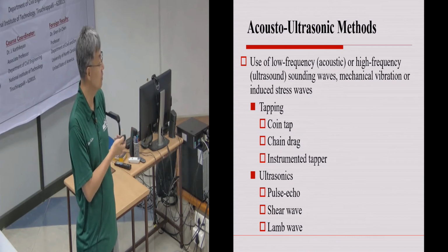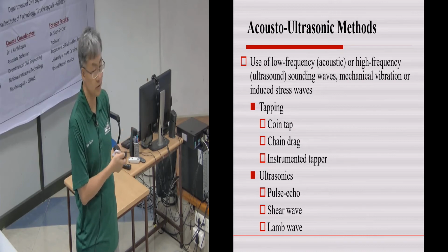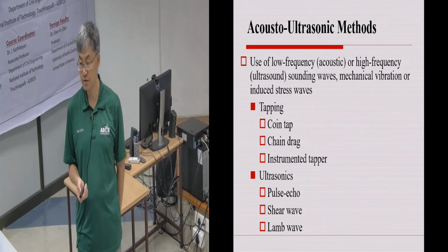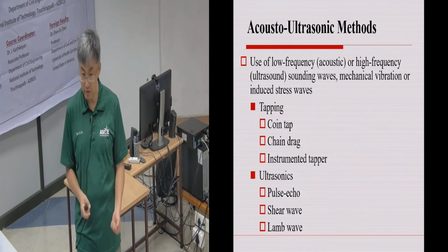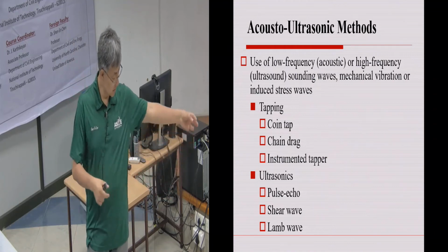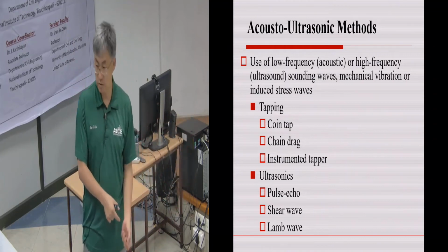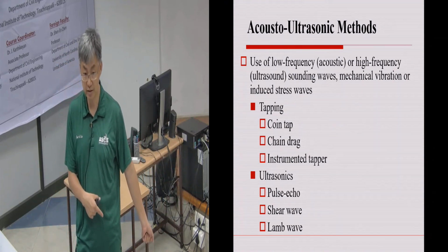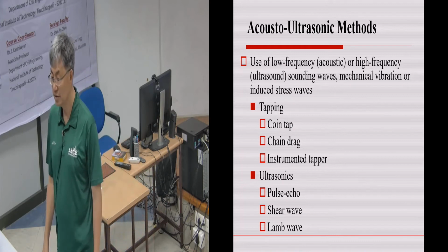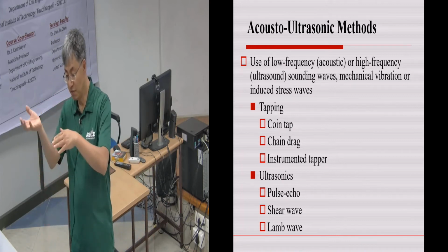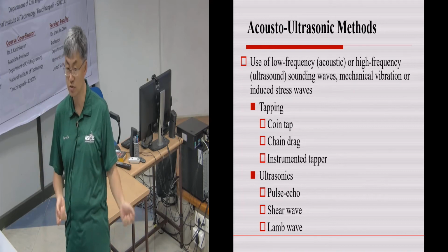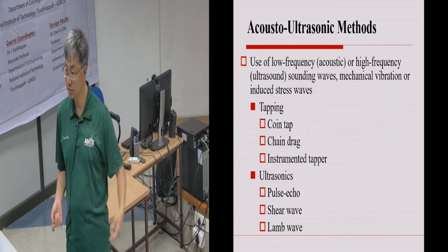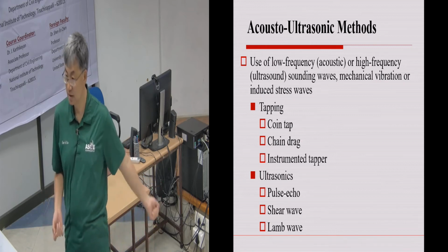Some traditional techniques like chain drag and coin tap are actually very useful. I don't know how many of you have experience with chain drag. It's literally a steel chain laid on the ground, and you just pull it. This is most often applied on a bridge deck, and then you just walk. If there's a void in the concrete deck, the sound will change. You have to have a trained ear to listen for that kind of sound change.